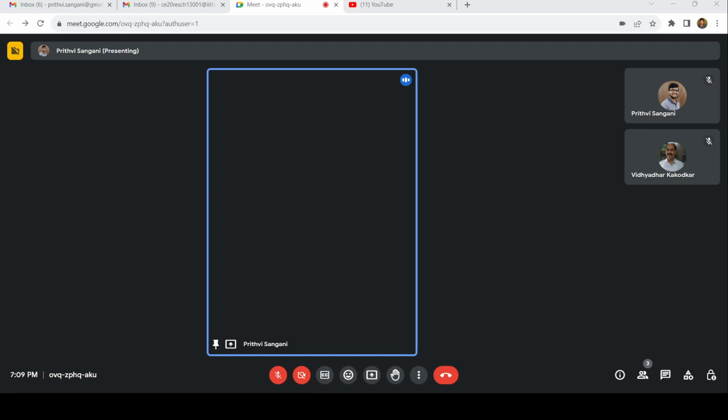Okay, so what happens to the rest of the members? For the rest of the members, there is no force here. There is no force at this roller support and this pin support. So if there is no force, this should go zero. So there are no forces in that. So this is my UI.